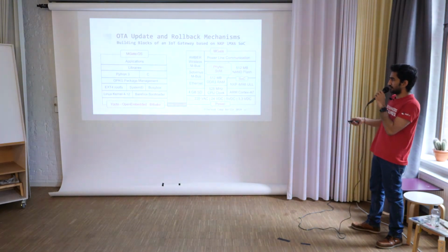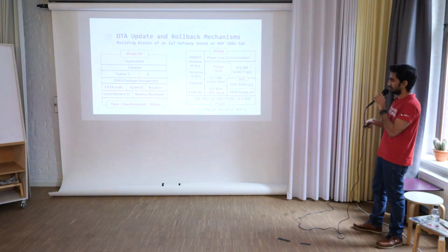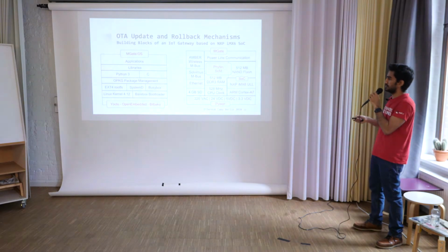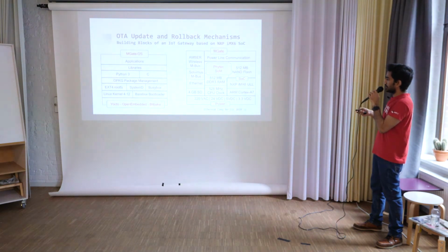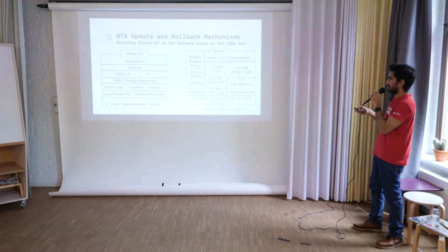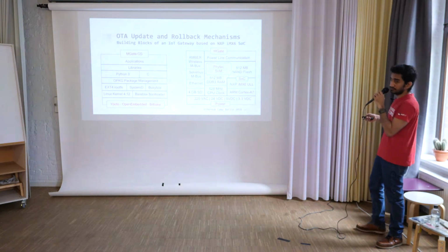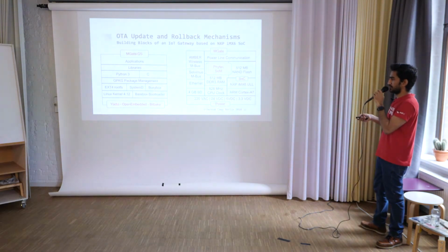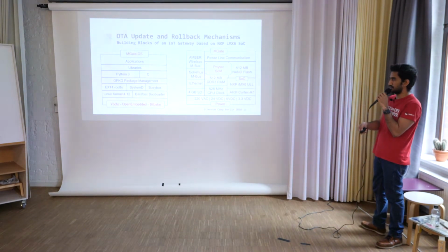And this is one of our products that we delivered recently to Take Evo. It's a multifunctional gateway, used for submetering. This is the hardware you can see, and we have many modules here. They have their own stack, and we have to find a way for them to be updatable by the processor. So you have to keep those lines, whether it's UART or SPI, so that it can release an update to these modules whenever we need. And basically, this is the operating system stack of that, built using Yocto.